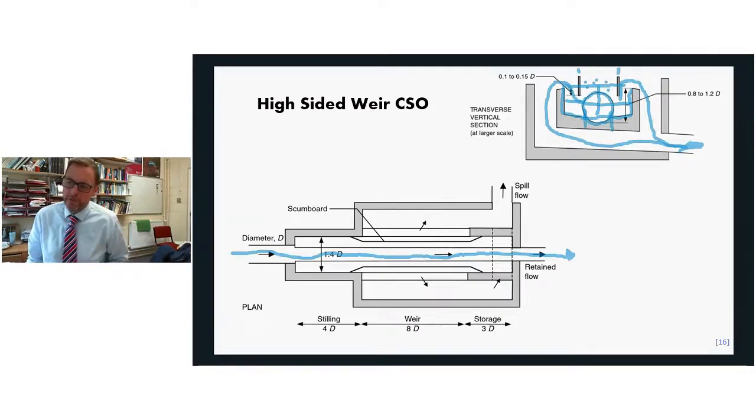They were designed so that if the flow got even higher, it would be up and off that way. And in that case, that's when you've got a really unusual flow. So then you're making a decision, right? In order to get the discharge capacity you need, you have to neglect the solid retention part of the design, which is not ideal.